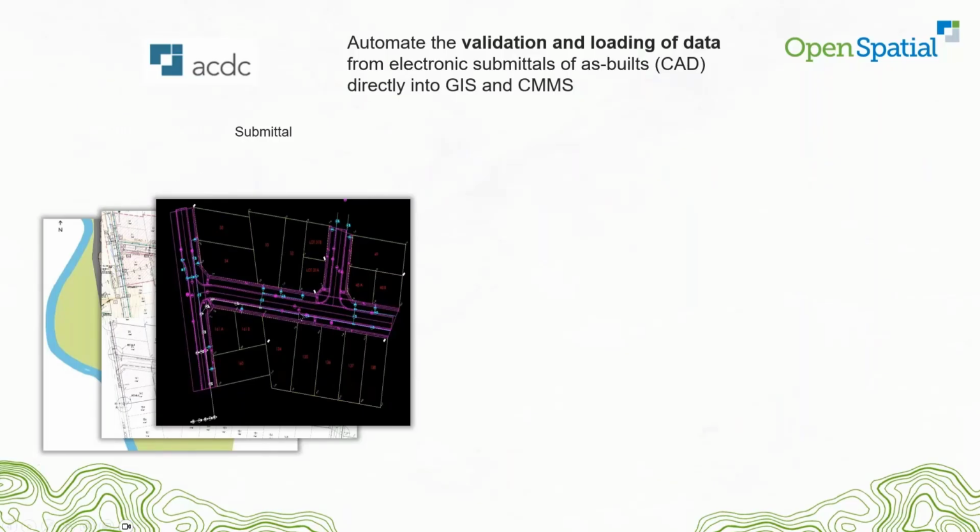On the spatial side, are polygons closed? Is everything snapped? Do we have isolated nodes if you're using utility networks? So you can't give me a hydrant without a stub on it, or you can't give me a catch basin without draining somewhere, or you can't put a blow-off valve of a water onto a sewer pipe, that sort of stuff. All sorts of weird errors.